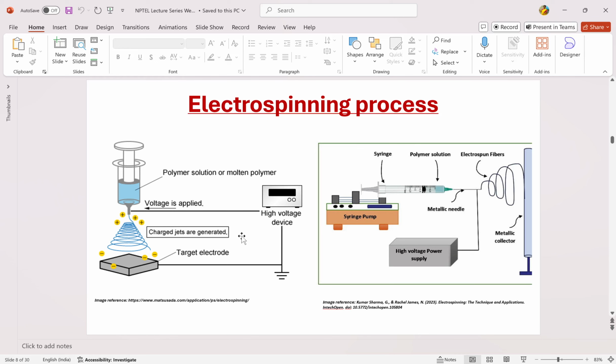So this is a setup of the electrospinning process. You can see two kinds of setup. One, the spinneret is on top and your collector is at the bottom, with a voltage supplier at the side. Another setup, on your right hand side, has a syringe pump which will push the piston of the syringe down so that it ejects the polymer solution through the metallic needle.